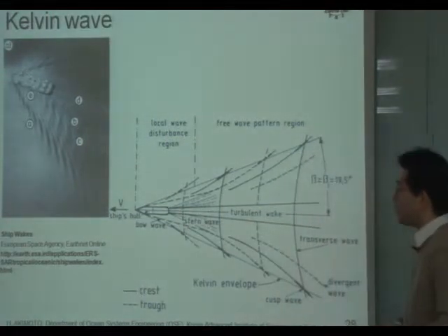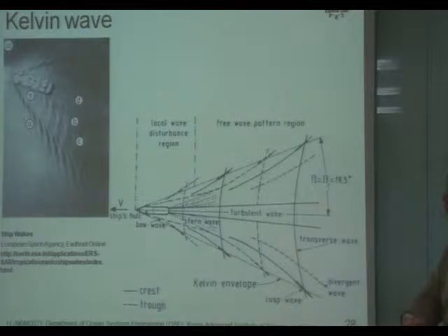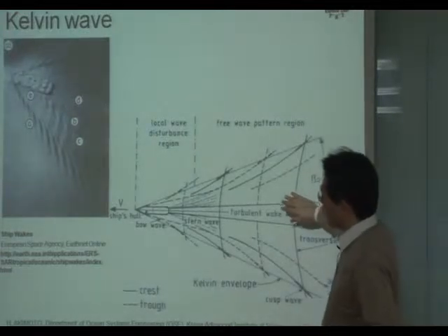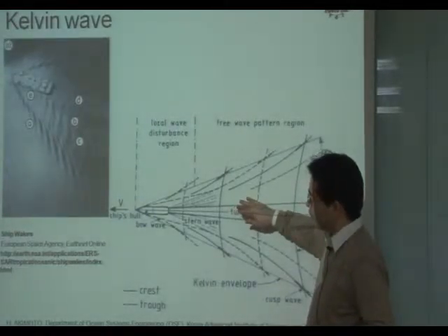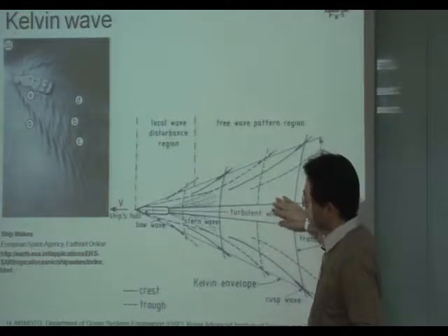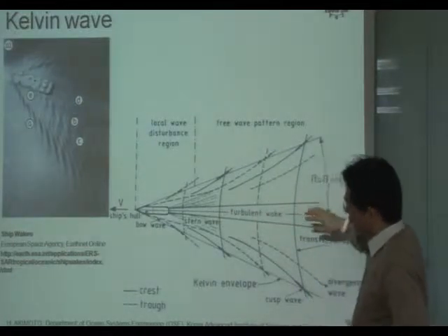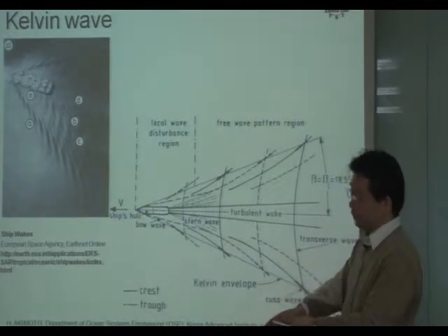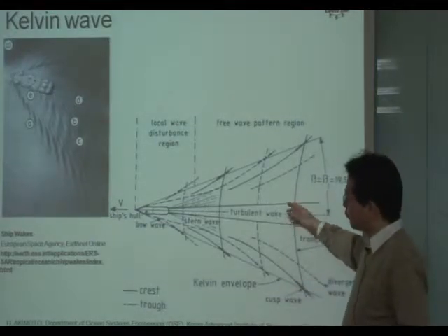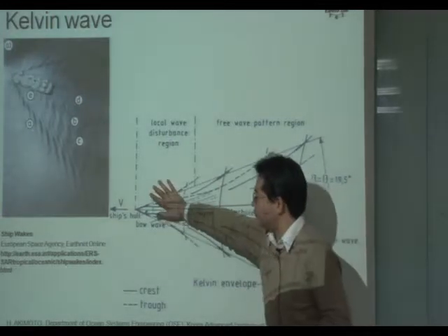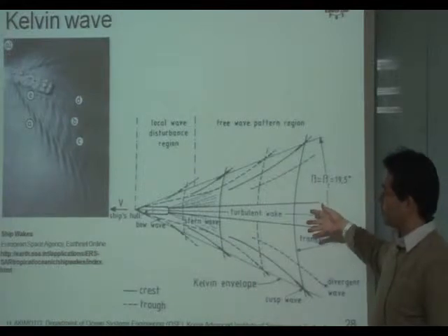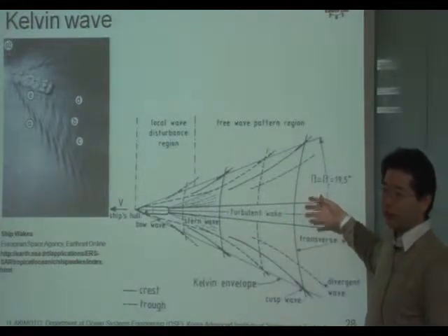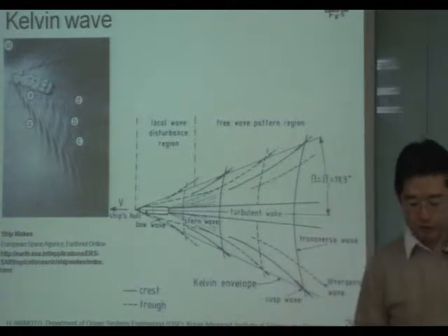The ship will accelerate the fluid particles around the ship, and after the ship goes, the particle motion still continues. So if you hide the ship part, you will see a water jet-like structure in the fluid.